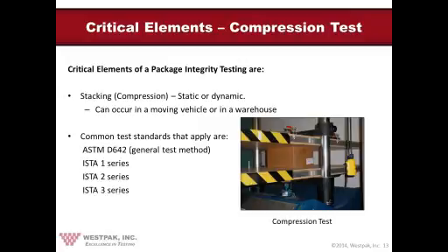Now, the ASTM D7386 or ISTA 3A incorporated what's referred to as a dynamic compression test, meaning a box is loaded with a top load and then placed on a vibration table and then subjected to a combined vibration/compression test. This simulates packages being stacked and shipped, and at the same time simulating a box at the bottom of a stack in a pallet or stuck at the bottom of a loaded UPS, FedEx truck and trailer.